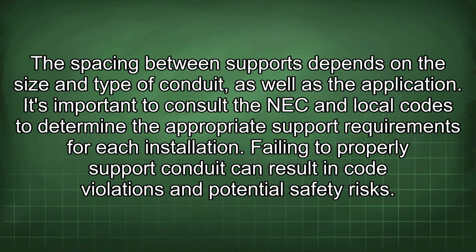The spacing between supports depends on the size and type of conduit, as well as the application. It's important to consult the NEC and local codes to determine the appropriate support requirements for each installation. Failing to properly support conduit can result in code violations and potential safety risks.